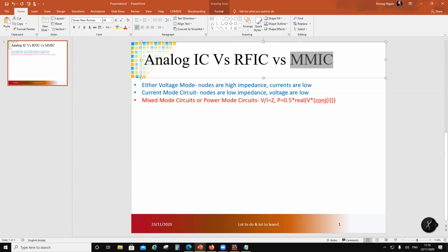While here, for example in a gallium arsenide process, the hole mobility is roughly 1/80th. For example, gallium arsenide has much slower holes. So basically, hole mobility is much smaller than the electron mobility. That's why you do not have P-channel devices here. Then you have only N-channel devices. So if you want to make logic using N-channel devices, it will be resistors as pull-up resistors and the N-channel device. So all the circuits would be designed as N-channel device circuits with resistors for pull-up or resistors for load.